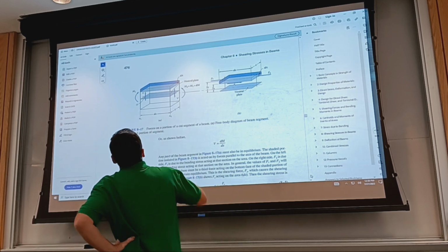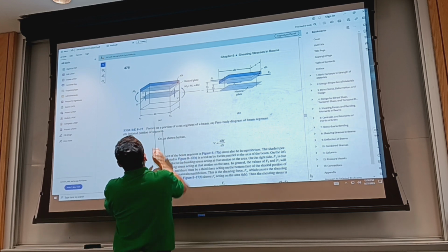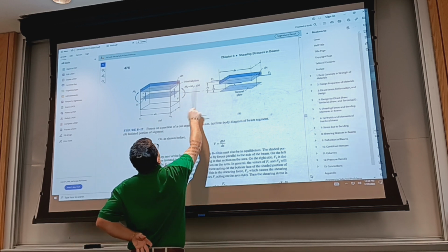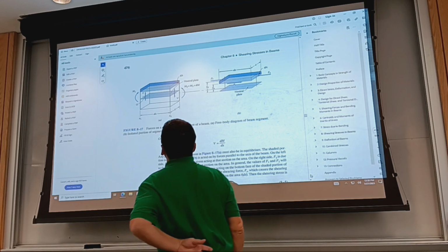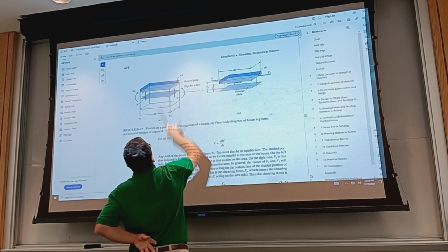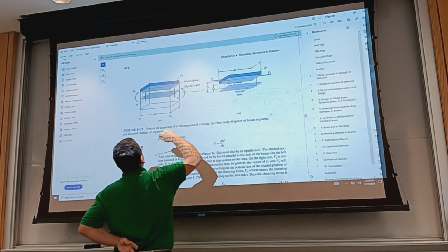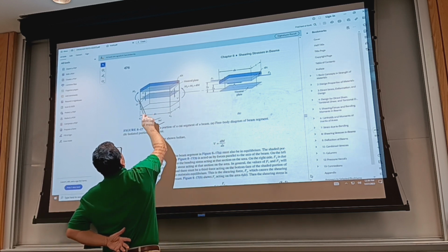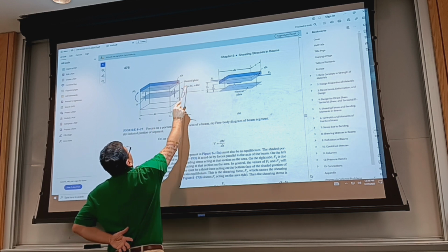So we have, like I said, equilibrium of that thin vertical slice through the beam, M1, M1 plus dM. We have the shear force V, which, as we already saw, is not evenly distributed. But in any case, these in addition maintain equilibrium of the piece, because I have more moment here than I have here.